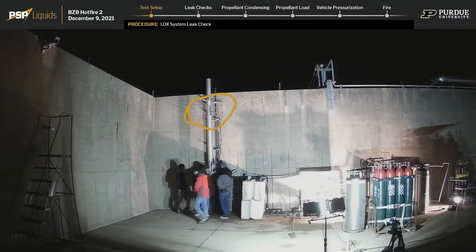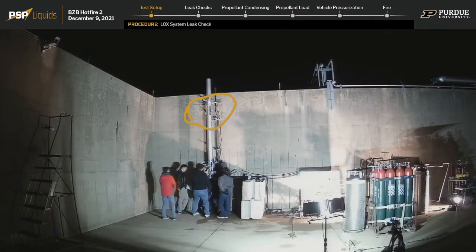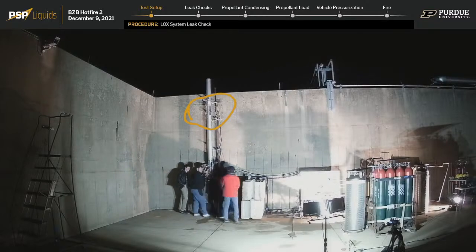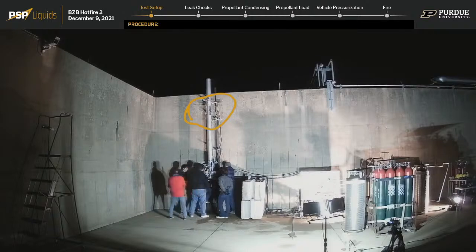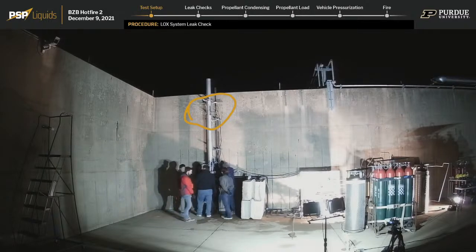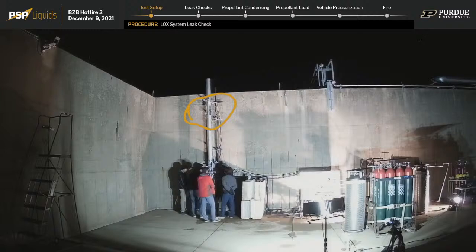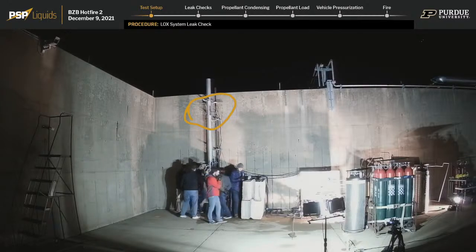Yes, the upper plumbing in the upper airframe or the mid airframe, it gets complicated. But yes, we see what you're saying. So in the upper airframe, this helium is diverted down into each of the respective tanks through a regulator, which reduces the pressure from 4,950 psi to the nominal 505. We tightened the loose fittings, so we're ready to check again. Over.